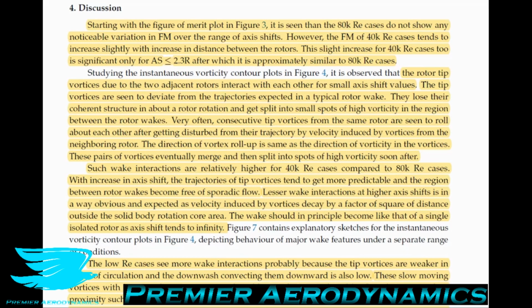Now, you could always reduce the amount of lift that you're producing at the tip. The problem with that is that rotors typically produce their greatest thrust at the tip as well, because that's where they're traveling fastest and all that. So you can reduce the lift, but then that's coming at a price of reduced thrust as well. And it's dramatic.